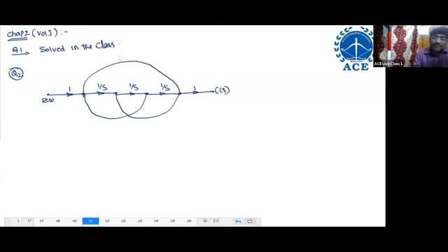This is the diagram. Find the transfer function. Here -1, this is -1. How many forward paths? 2 forward paths. One is straight, like this. Second one is through 1 by S. How many loops? This is one loop L1, this is L2, second loop. Third loop is like this. This is the third loop. Here not touching third loop. This is not a node.